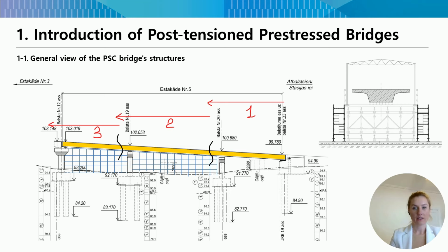After this stage, the scaffolding might be dismantled in the first constructed span. That is how we can save money on renting the scaffolding and move it to the third span, the last one. Then we do the same with the third segment of the deck, repeat cast and stressing. So all the deck is cast in tension. Then we do grouting, injection of ducts. After all, dismounting of technological shelter and deleting scaffolding.